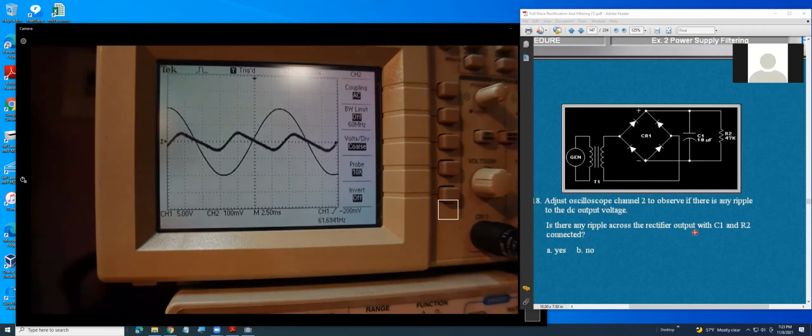You want a fast fill, then a fast discharge, then a fast fill again, right? At the output, you want it to be flat. I don't want ripple. When they discharge for a very short time, they are already charging again. So that makes it constant, and the ripple will be smaller.